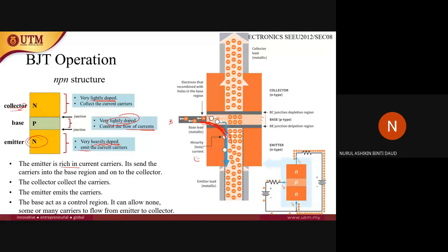Since some of the free electrons flow here, they will combine. This will make a recombination of holes and electrons. So there will be a small percentage of free electrons injected into the base region that combine with these holes and move as valence electrons through the base region.